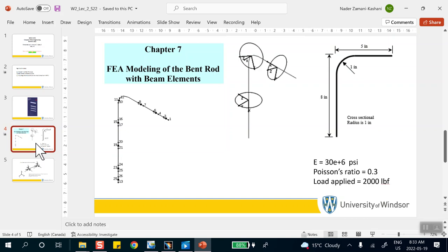Because if you do beam problems, like you did in stress analysis, something is going to give in, okay? For example, the stress distribution is not going to be exactly what the real-life stress distribution is, okay? Deflections are okay. Bending stresses are okay. The MC over I, MY over I, those are okay. But there are shear stresses. There are other things that in beam bending we ignore.